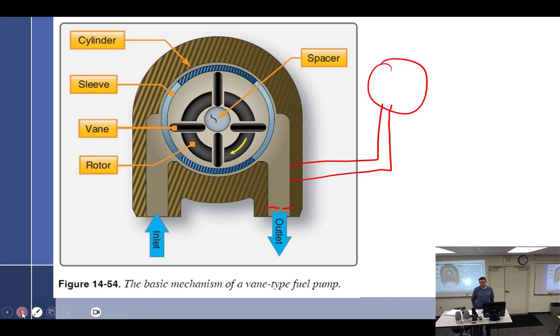And then to start it, you typically have either a primer, or if you start it with the butterflies pretty much closed, we know that there's enough vacuum on top of it. It draws fuel out of the idle jets, and you get fuel and the thing starts, right?